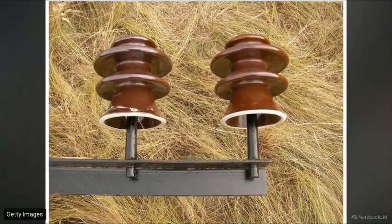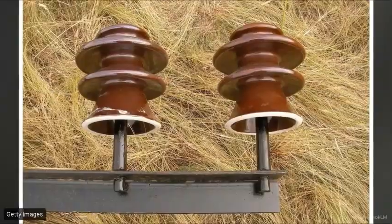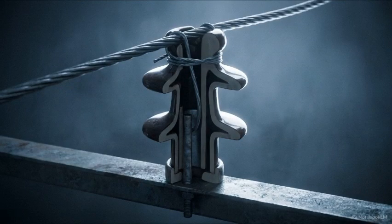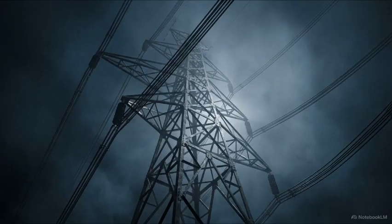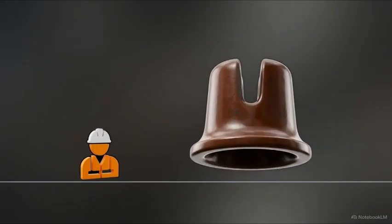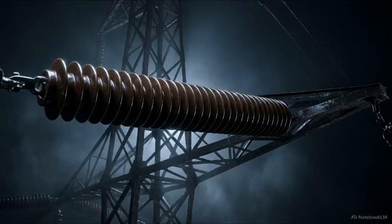For lines up to 33 kilovolts, a single solid pin-type insulator is sufficient. The conductor is tied into a groove at the top, using the ceramic body to isolate it from the crossarm. However, scaling this design for higher voltages is impractical. To block 132 kilovolts or more, a pin insulator would have to be so large and heavy that it would become too expensive to manufacture and too bulky for a standard tower to support.